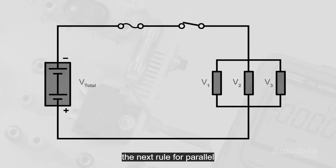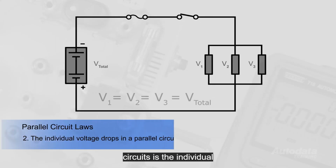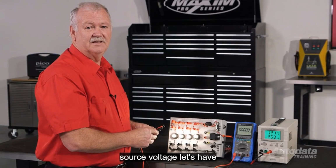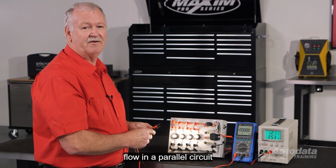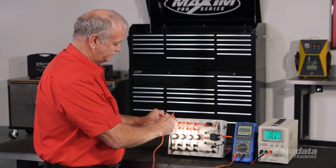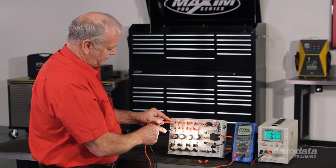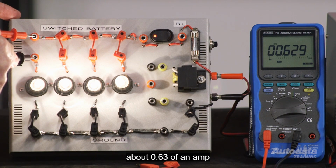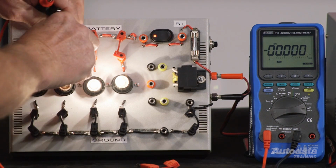The next rule for parallel circuits is the individual voltage drops in a parallel circuit equals the applied or source voltage. Let's have a look at the current flow in a parallel circuit. In globe 1, we've got about 0.63 of an amp.